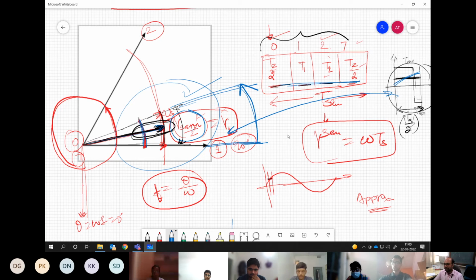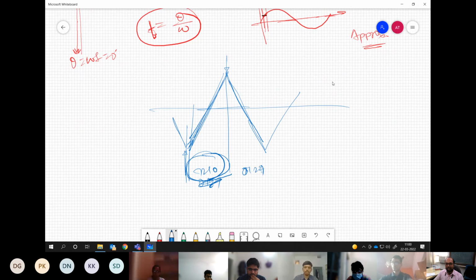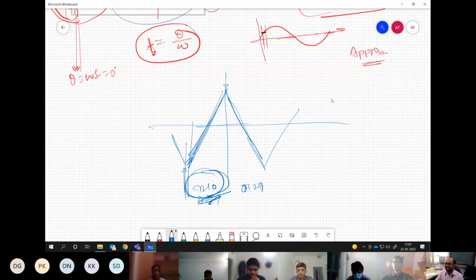But sir, this is double sampling, right? Whatever, if in each subsection we take two samples, then it is double sampling. The sampling is what we are basically doing at the peak and valley of the carrier, correct? Each sample we have correlated with the space vector, as applying one of the sequences.